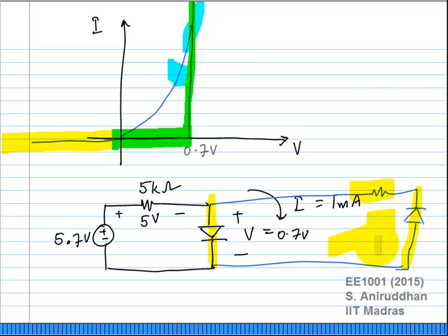If you apply 0.7 volts, you have to get a current through the diode. You see how you will have many permutations and combinations. You can work out what the solution to the circuit should be just from very simple KVL, KCL. Any questions so far? This is just a simple way. We do not expect you to solve the exponential equations in the exam, obviously, or even in the tutorials, unless we ask you to check something. This is not routinely expected for hand calculations.